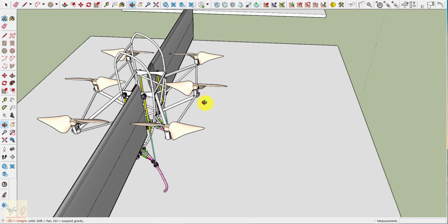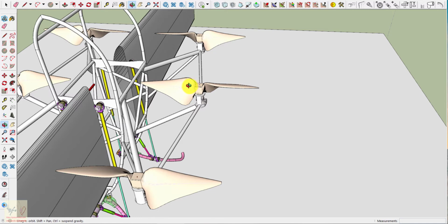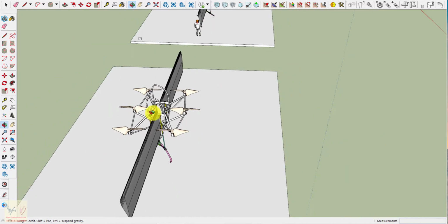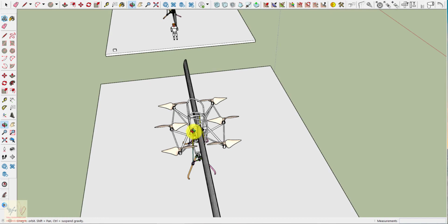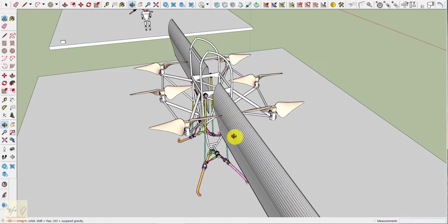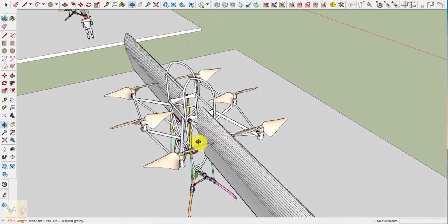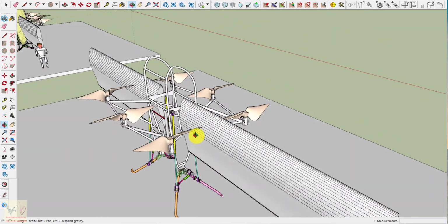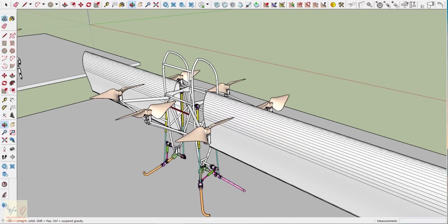The propeller spins around and moves the air. That activity generates a force on the propeller from the air, and that force is considered as lift. And if you take the weight of this whole structure with 6 propellers and divide it by 6, and you get that amount of lift from each propeller, then you have enough lift for the structure to lift itself up off the ground. And actually, you want more lift than the weight of the structure to get it to go up in the air and to actually get it to accelerate up in the air.